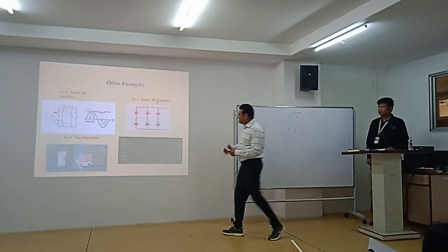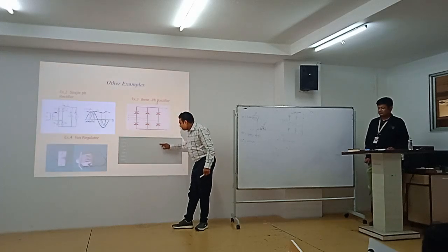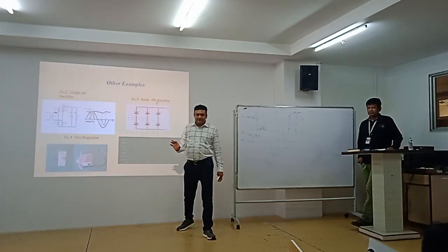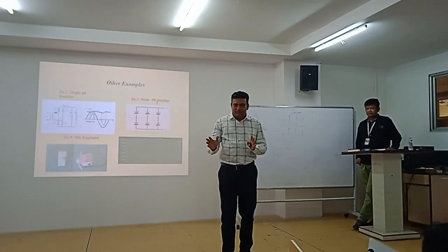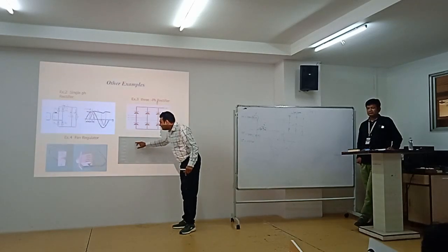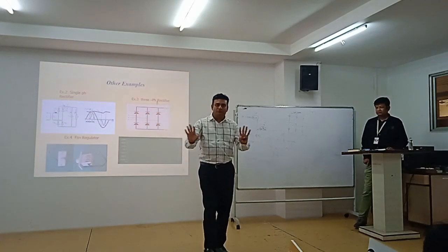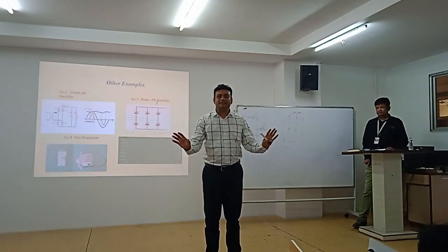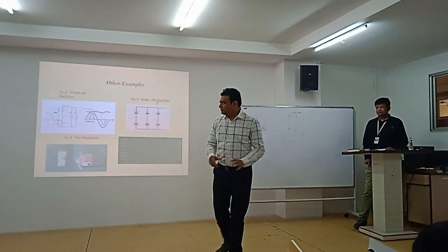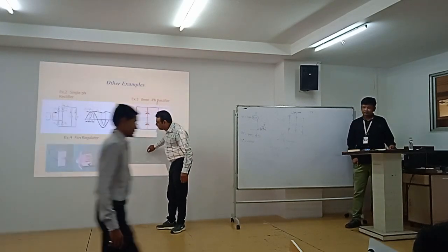But these all are here. Here you can see this is a double hump. So it is a converter or rectifier. If you use SCR as a converter or rectifier, then there will be a double hump per cycle. It's a general tendency. You have to keep in mind. Okay, this is a tendency. Right? Okay. So, three-phase rectifier, its output waveform.